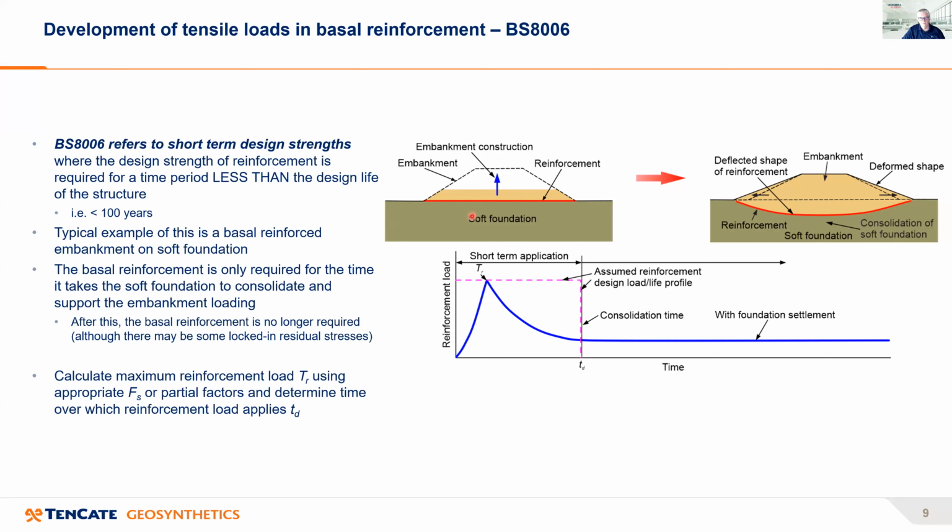So here we have the embankment constructed on the soft foundation with the basal reinforcement. Then as we place the fill on top of the reinforcement to build the embankment, the tensile load in the reinforcement, which is this blue line down here, increases as the embankment gets higher. And it reaches a maximum when you've constructed the embankment to the completed height.